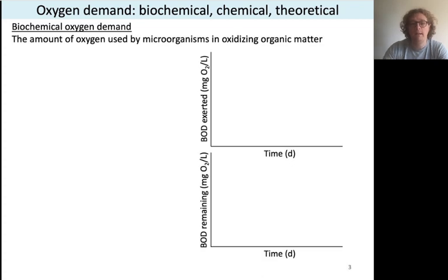Okay, so BOD, biochemical oxygen demand, writ large, is the amount of oxygen that will be used by microorganisms as they oxidize organic matter. In other words, these microorganisms are going to break down organic matter to derive energy from it, and as they do, they're going to respire, just like you and I are doing right now. So we will take oxygen, in our case, into our lungs. For a microbe, they'll be using oxygen from the water column as part of the reactive process.